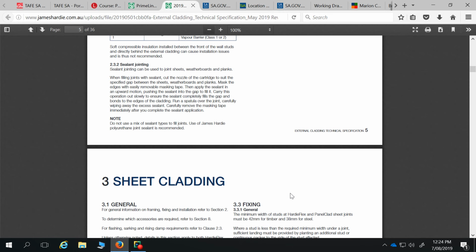Drafting patterns and model patterns, there's two different things about them. Model patterns actually will be true to its representation even when it's orbited. A drafting pattern will always stay horizontal on the screen. So if you've ever done maybe a pattern on the roof and then you orbit your model and it still looks like it's going the wrong way, that's because you've chosen a drafting pattern.